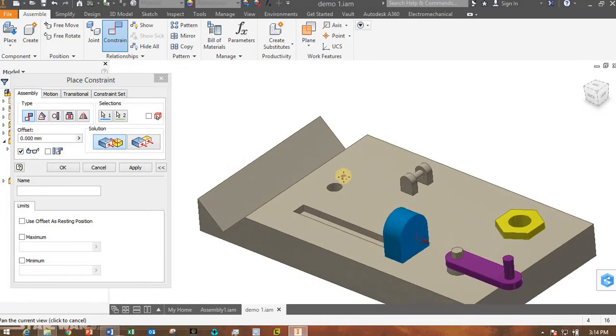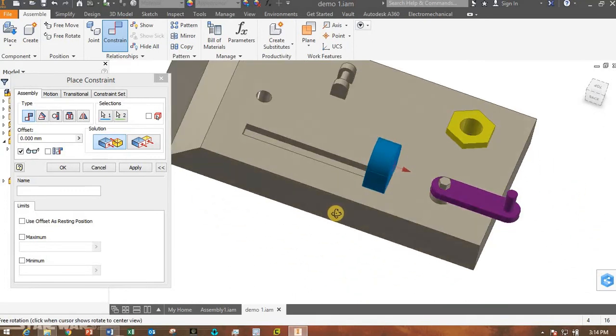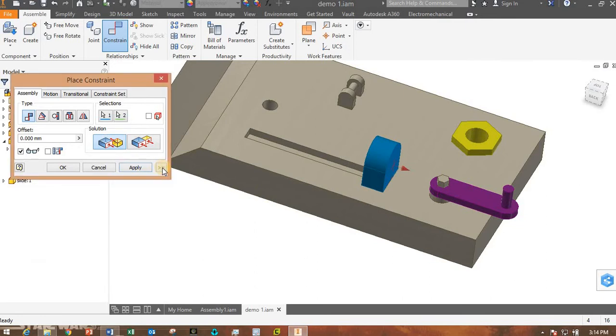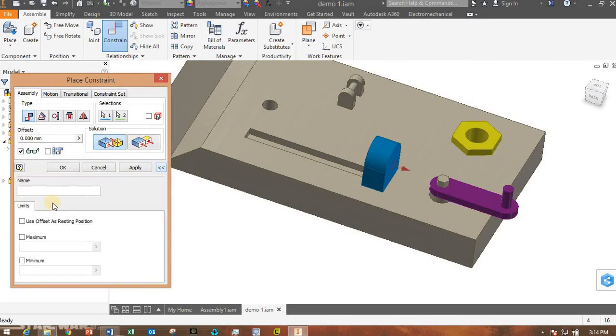Now watch this. Right now it's fixed on this end. Now there's this thing called limits here. Maybe yours is hiding. If you click these 2 double arrows here, you'll see these limits pop up. You can click on a minimum and a maximum here, so I can set different distances. Watch this. Let's set this distance here to, I don't know, 20.